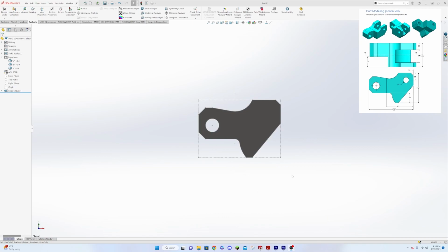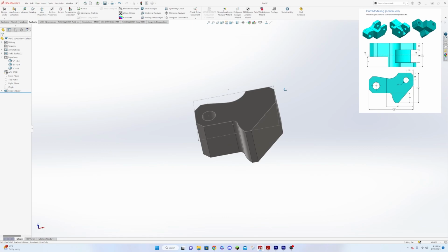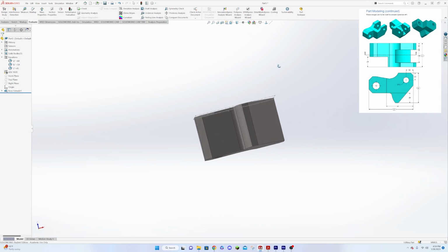All right, so we have our object here, right? And we're drawing off of this plane. And so we can see that we've got a few things that come off the front plane. If we look at the piece, if we tip it over and we're looking at it like this, our slot is going to be measured 12 millimeters off the front, and we're going to have this one little notch cut that comes off the front as well. So actually both of those notch cuts are going to come off the back. So what we might do is,